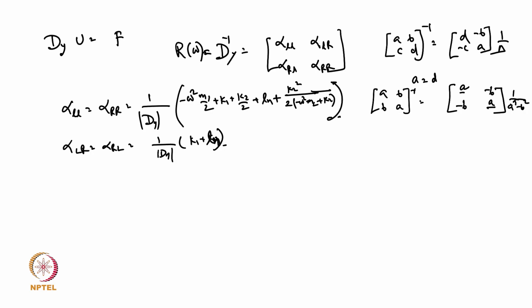Now the question comes: once we get that receptance matrix, what can we do from here? For the unit cell, for any monocoupled system, we can rewrite the force displacement relationship this way. We write the force displacement relationship as dl, dr, the left side. You can think that is the unit cell.